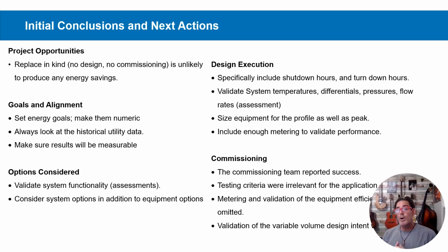During design, there are a lot of things that we need to do, right? We should specifically talk about what the operating hours are, what the shutdown hours are, the turn down hours are, what the temperatures are, the differentials, the flow rate. All of those design details need to be complete for a good energy design.